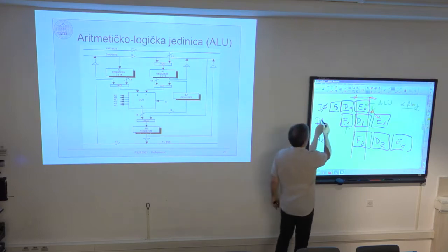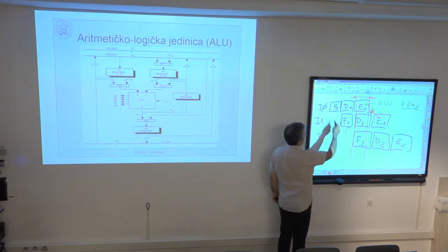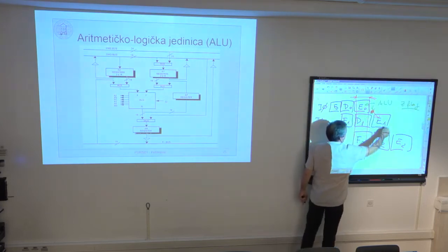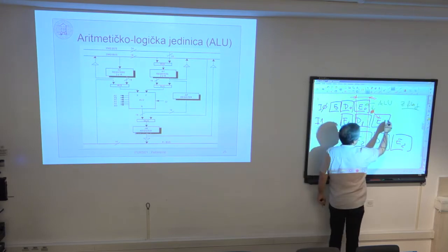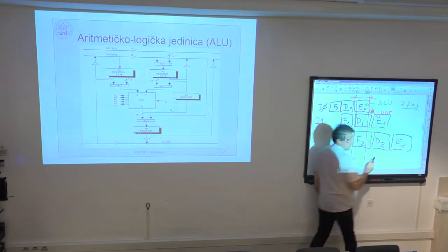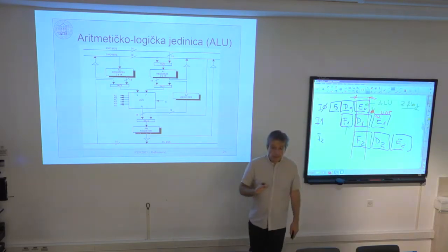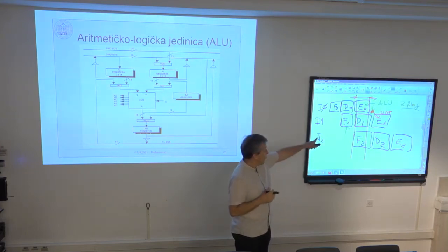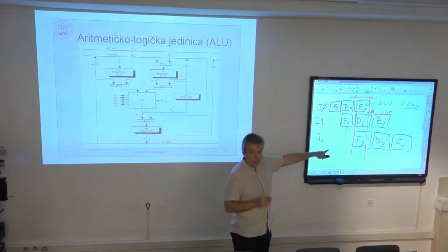This I1 is a conditional instruction based on the condition set in the previous instruction. The condition is set here, but what I do is simply execute instruction 1 or not. That's the idea. So it is not a branching; simply the final phase of I1 is either executed or not. That's the only effect of this conditional execution.